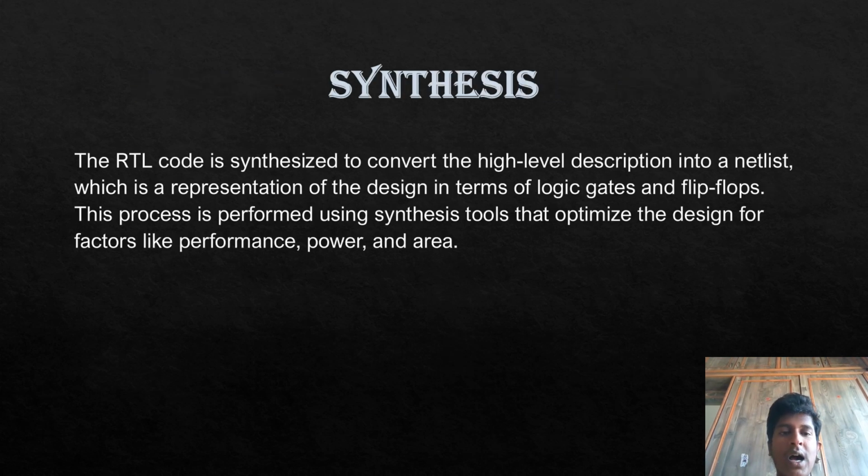Synthesis. The RTL code is synthesized to convert the high-level description into a netlist, which is a representation of the design in terms of logic gates and flip-flops. This process is performed using synthesis tools that optimize the design for factors like performance, power, and area.